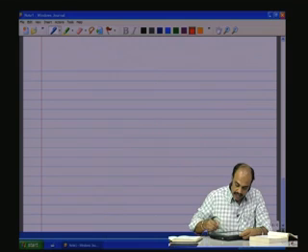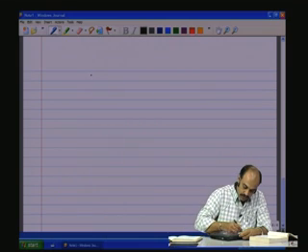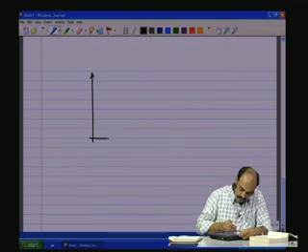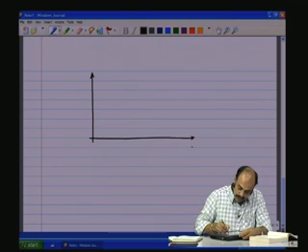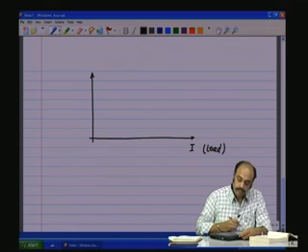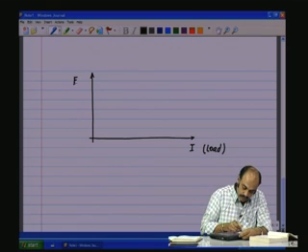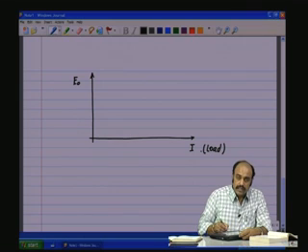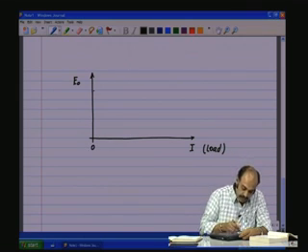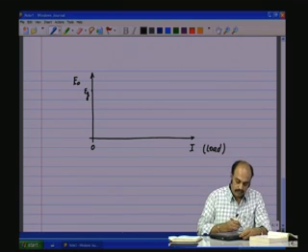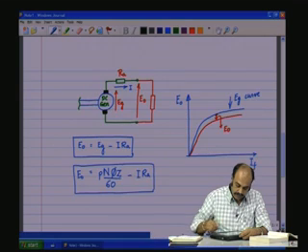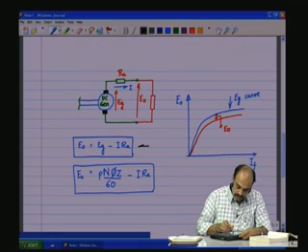And with respect to I, we have the voltage regulation curve. I is the load, and you have E naught. So, when the load is 0 here, no load resistance connected, E naught will be the same as Eg, as is evident from this equation here, when I is 0.